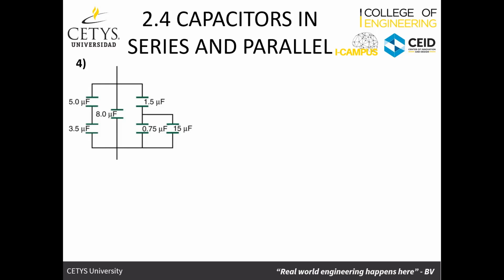So notice that there are these 2 lines here in the circuit. These 2 lines represent where I'm trying to measure the equivalent capacitance. Or in other words, if I were to have the device and have the two terminals, the black and the red terminal that we were talking about, this is where I would put it to measure. The measurement of the capacitance can be different depending on where I'm placed. So we always have to keep in mind the lines when we're doing them.